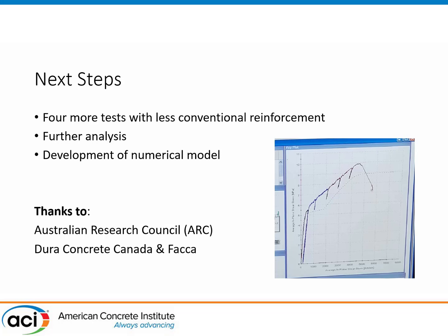We had 4 more tests after that one, 2 of which have been performed so far. The second one had reinforcement in only one direction, and in that experiment, which was recently completed, so I can't show you yet, that meant that there will be a shear demand on the crack. That did not seem to change the behavior, which is good. The third experiment, we're trying to understand exactly what it meant and how it behaved, so I'm not going to tell you about that one either. And the next 2 have yet to be cast. We're going to do further analysis of the tests and develop a numerical model.